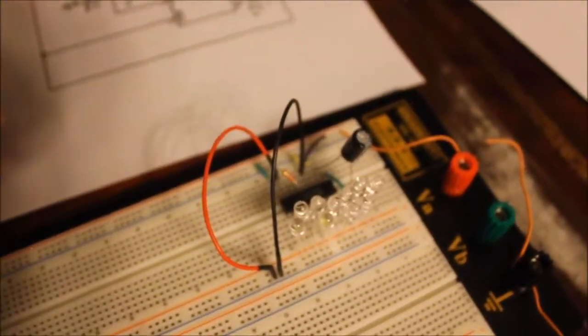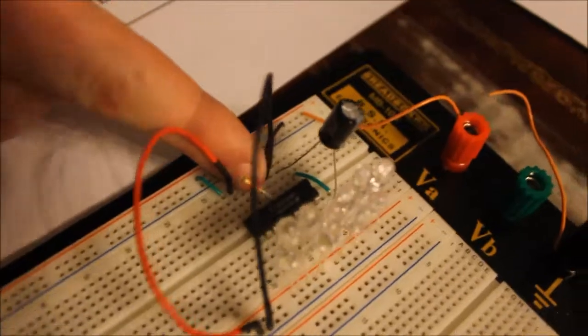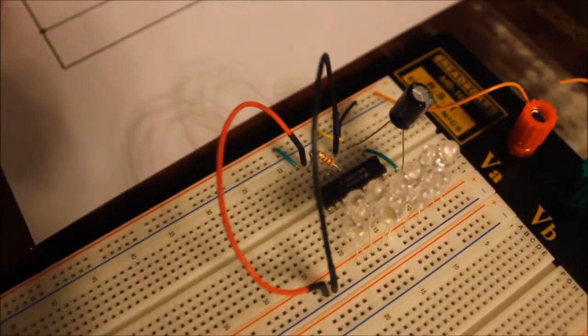Essentially you'll have to construct this circuit, solder it together, and then solder the signal pin 5 here in parallel with the left to right audio output signal, and then create another VU meter and connect it to the other audio output signal.